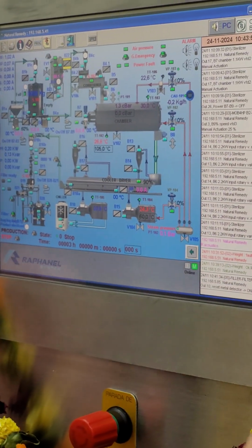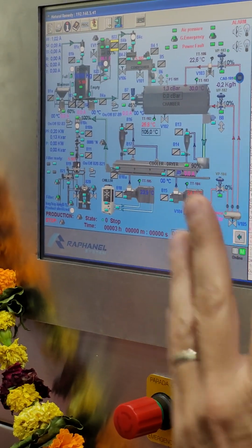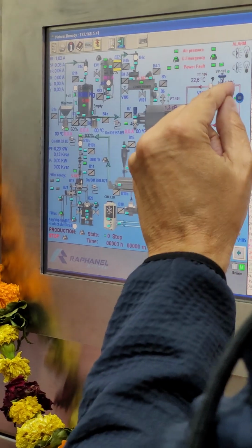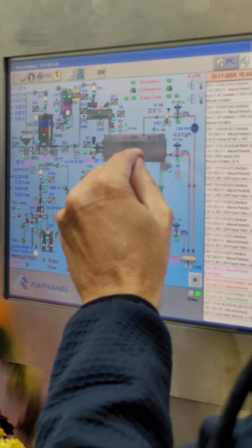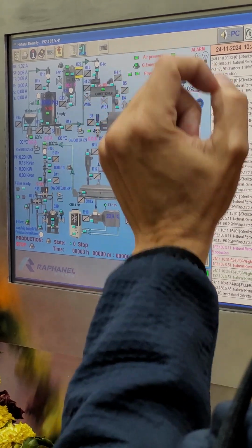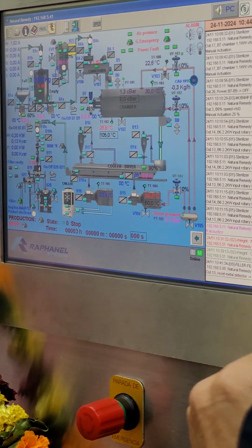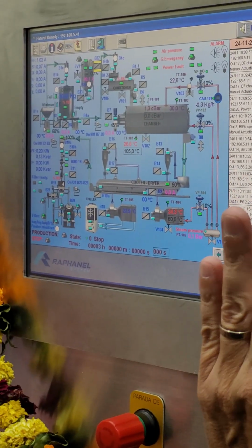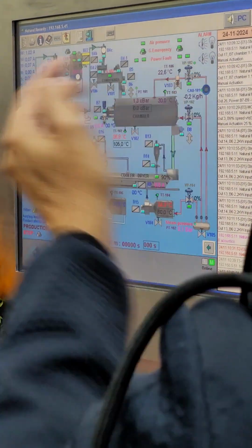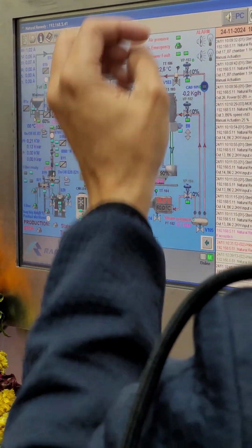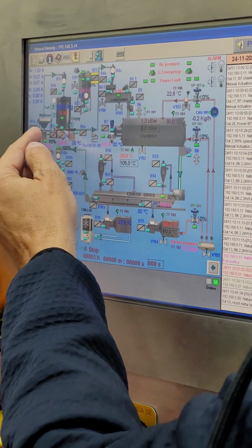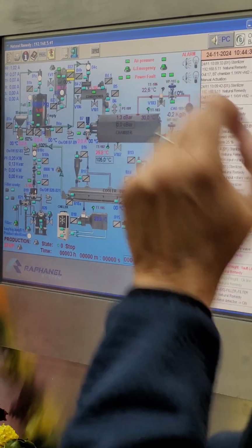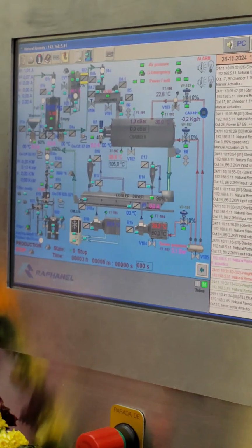The same happens if you... This is important. I want to explain because several things are possible that happen. If you are injecting steam, it's necessary that the quantity of material inside be correct. Quantity of material. And then if you, for instance, modify the time to load the line, you cannot do it. You put only 3 seconds. In 3 seconds, you start to move the material. In 3 seconds, the material is not here, and the chamber doesn't have enough quantity. You inject all the steam, condensate and water here, problem.